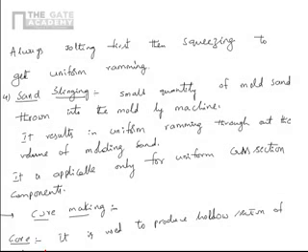Instead of that, suppose I need a cylinder where the inside is also a hollow space. For that, preparing the pattern is difficult, right? Once you insert the pattern in the sand mold and fill it, how do you remove it? You can't.